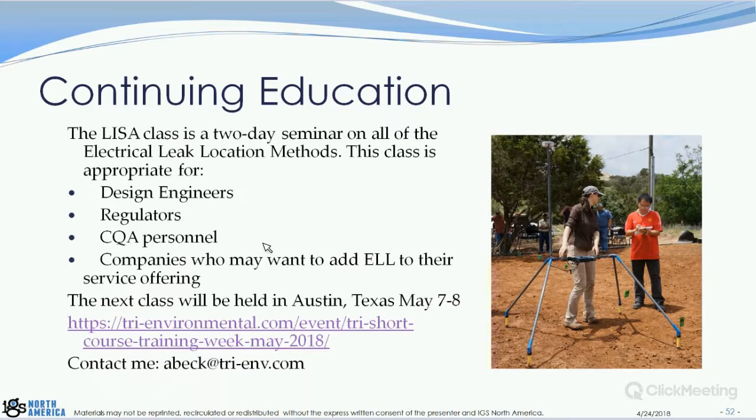Another question: does the method work for conductive geomembranes? It depends on what you mean by that. If the geomembrane itself is overly conductive, then it may not work. We have developed methods that work on EPDM. If you mean conductive backed geomembrane, absolutely it works, and we ground to the conductive backing on the HDPE geomembrane. However, when you install that conductive backed geomembrane material, if you don't isolate the overlap flaps in a proper way, those overlaps can conduct. They can be a short circuit and a ground that carries the current from inside the survey area to outside the survey area. That's a whole different topic. In fact, at the upcoming ASTM meeting, a guide is going to be drafted on how to install conductive backed geomembrane so that it is electrically isolated, in order to enable all of these methods.